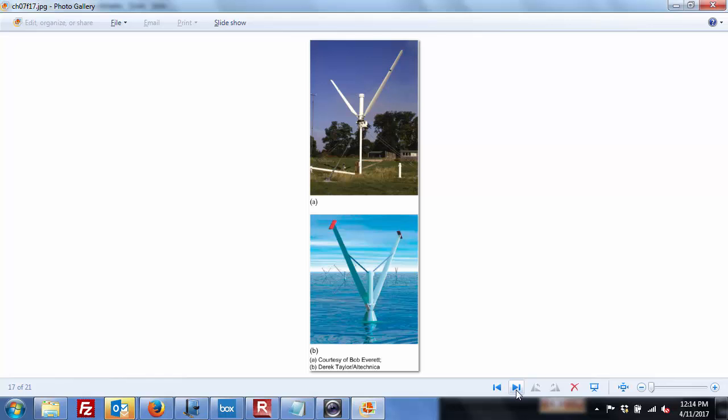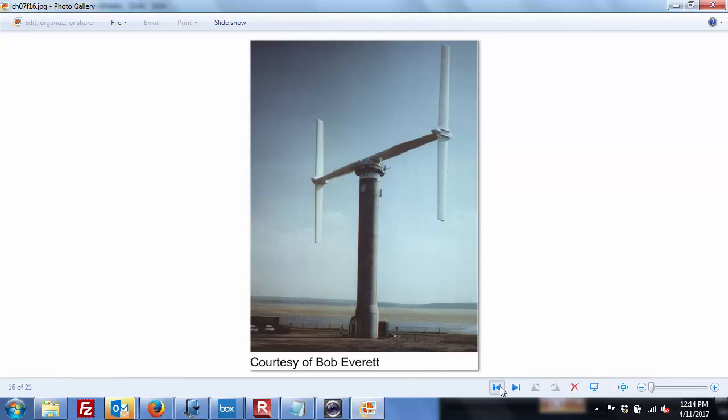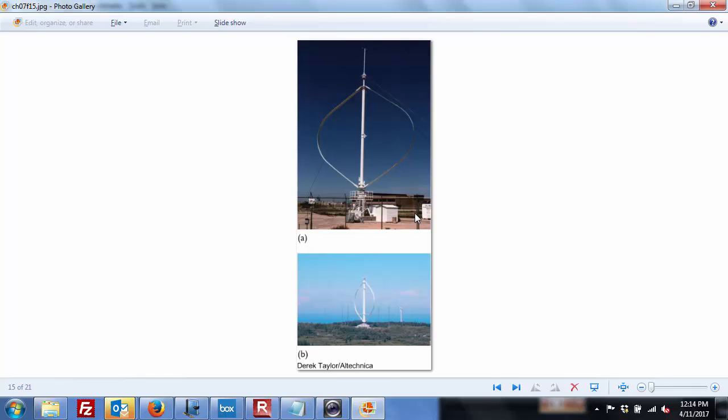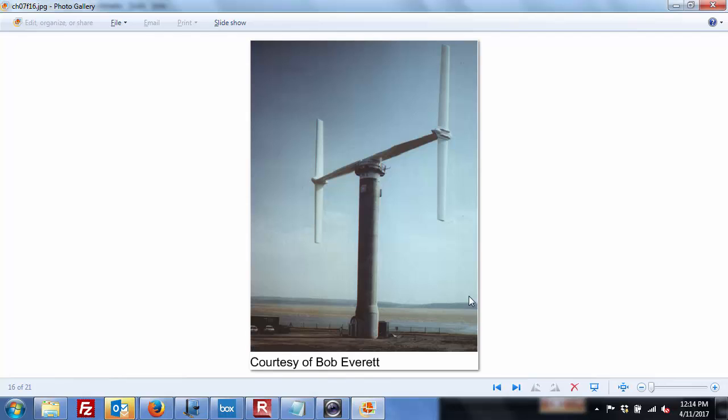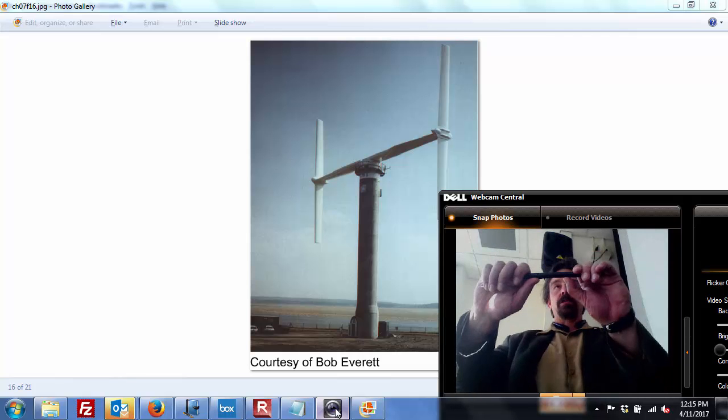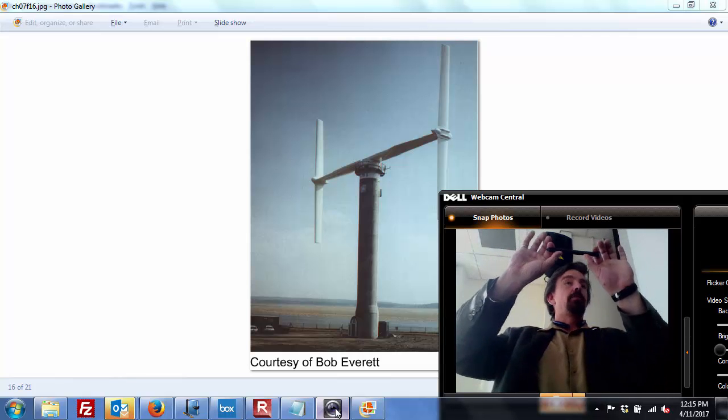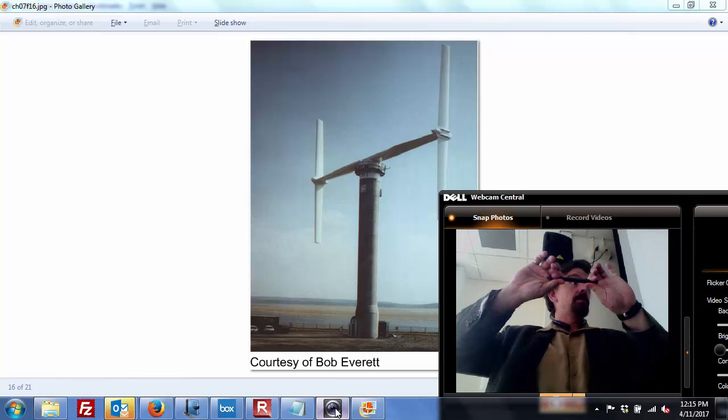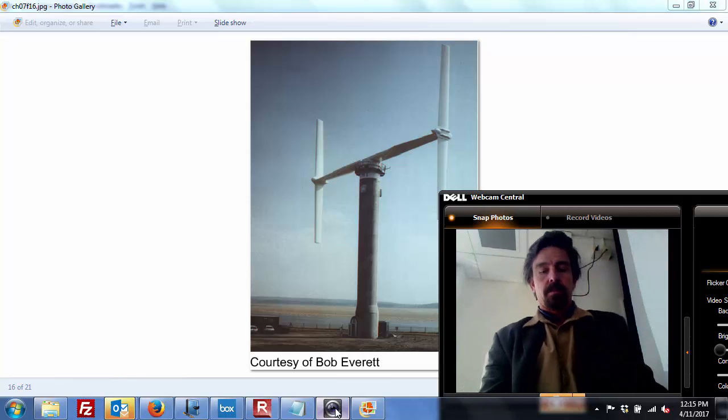If it's shaped like this spherical shape, it sends some of the excess force inward. As it spins, this portion is in tension, which is a favorable loading mode, whereas when this starts bending, it's in bending. It's like taking your pencil and snapping it. Much easier to break a pencil like this than it is like this.